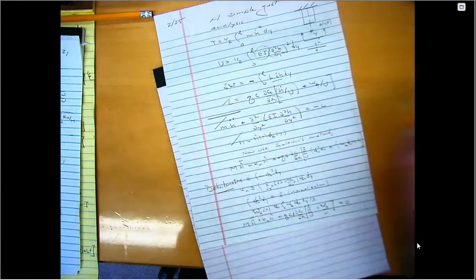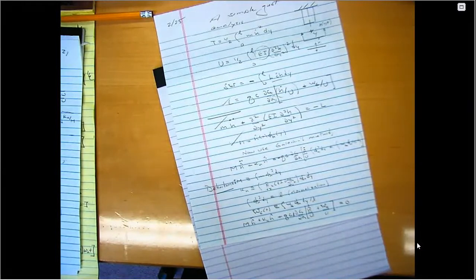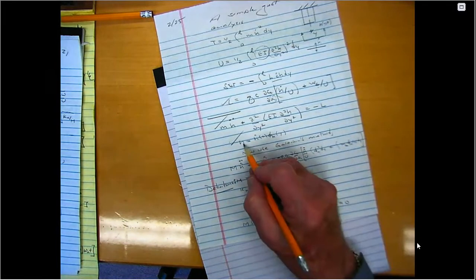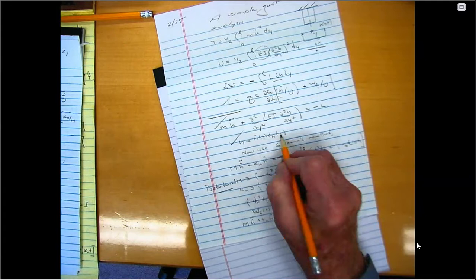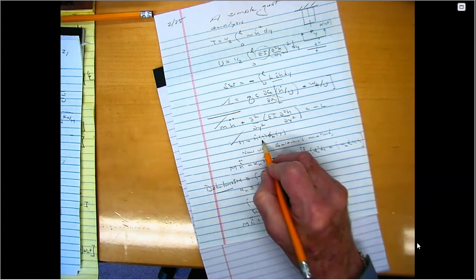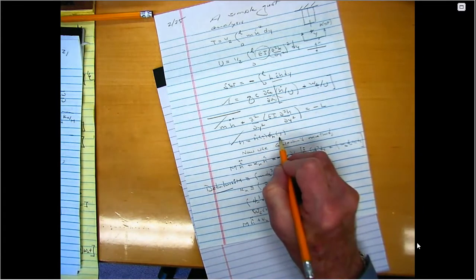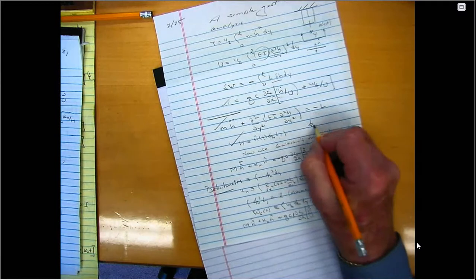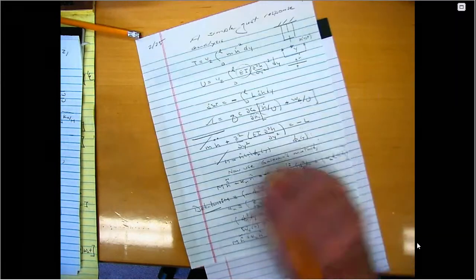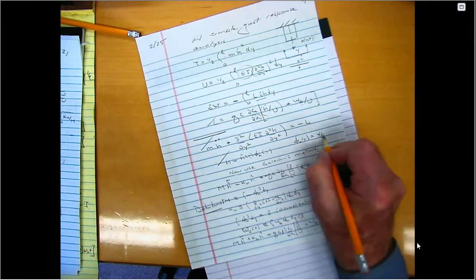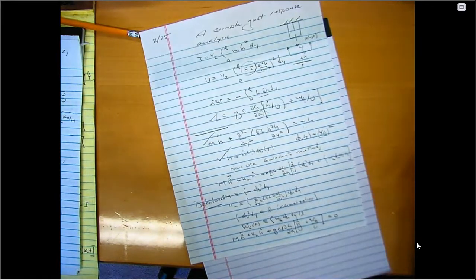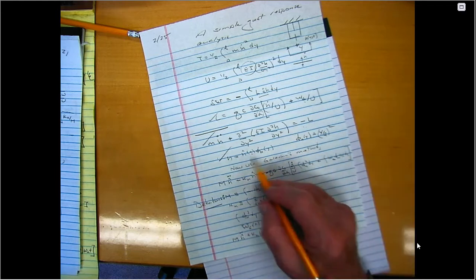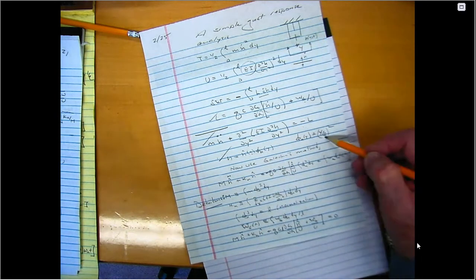Okay. Next thing I'm going to do is use Rayleigh-Ritz or something like Rayleigh-Ritz. I'm going to assume H, which depends on t and y, is some function of t which I don't know but hope to find, times some function of y which I'm going to choose. A simple assumption would be that this is equal to (y over L) squared. Why would that be a good choice? Well, I know that H should be 0 at y equals 0, which this certainly is.